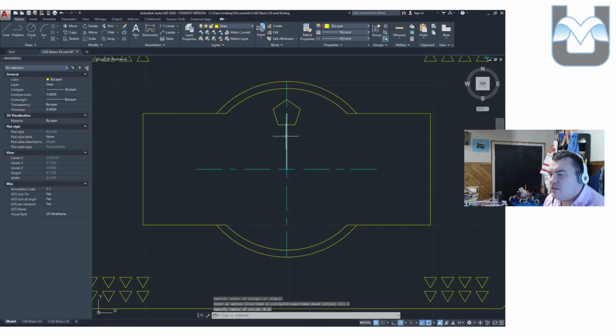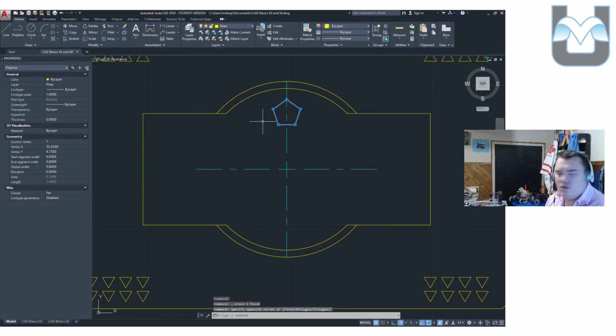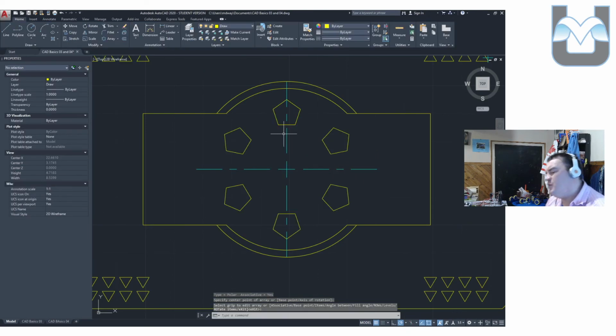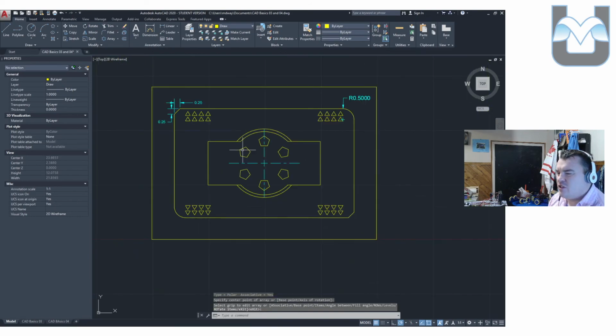Awesome. And the last thing we're going to do on this drawing, just to finish it up, I'm not going to do the corners or the circles on the corner because you know all the things you need to know for them. They are circles that get trimmed in certain unique ways. What we're going to do is put a polar array on this one, and we're very simply going to polar array this around a few times and press enter. In that case, the defaults actually do work.